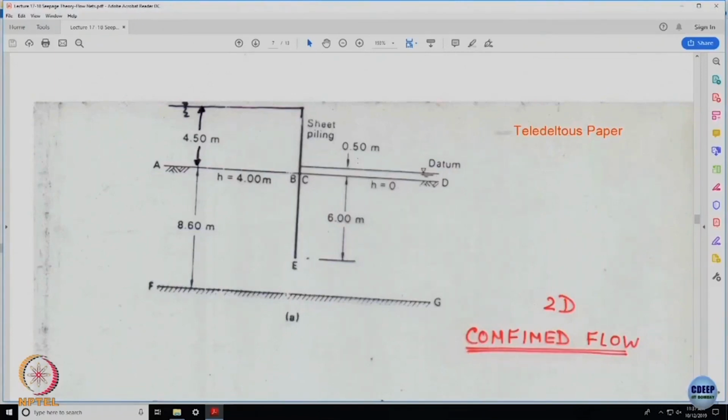So, the moment this sheet pile is inserted, it is holding a certain water column. I used the word bulkhead some time back. This is the bulk, clear? Any fluid, any mass which is being stored above the ground surface becomes a bulk. So, bulkhead is nothing but a sort of pile which is helping you to retain a certain volume of the material. So, ultimately I can store water up to this height. There is a downstream side, because the moment you have inserted this, you have created a hydraulic gradient.